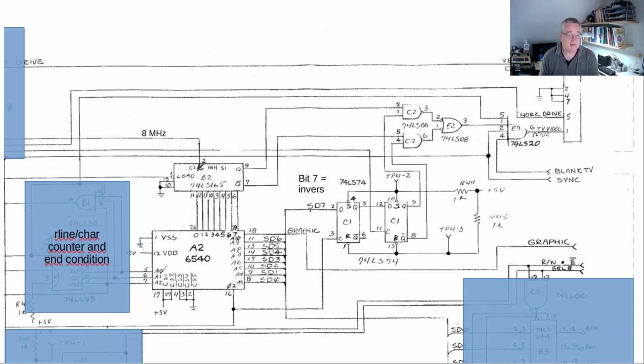So the 7th bit is delayed here by, let me guess, 1 or 2 clock cycles, and then the positive and negative bit is set here to the end, one with the positive and negative output of the shift register, and then those are NANDed, and then they go into the video output. This is, I think, display on here, and some other sort of stuff here.